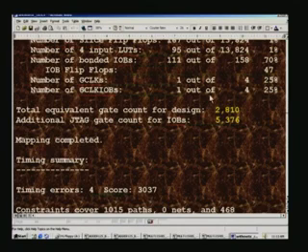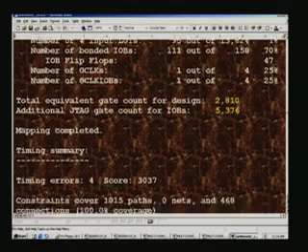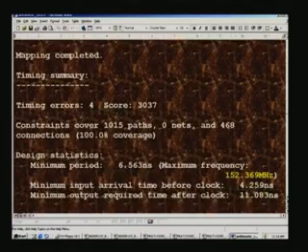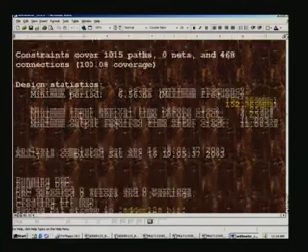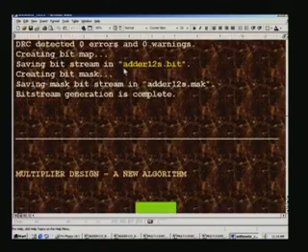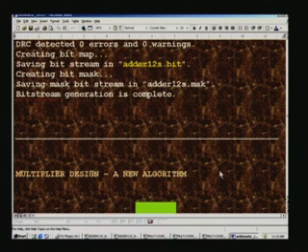What is of interest is the number of gates standardized to, say, 2-input NAND gates, and it comes to nearly 8,000 gates for a single adder, which adds 8 numbers of 12-bit signed numbers. And now surprisingly Xilinx reports a much higher frequency here, say 152 megahertz, and also produces a .bit output, the bit stream output.